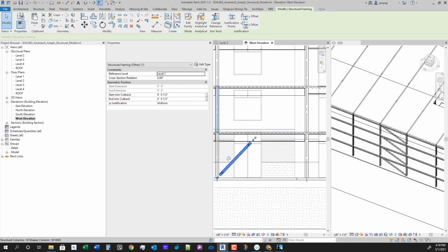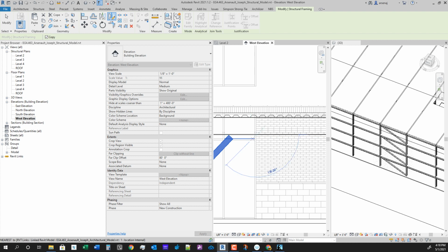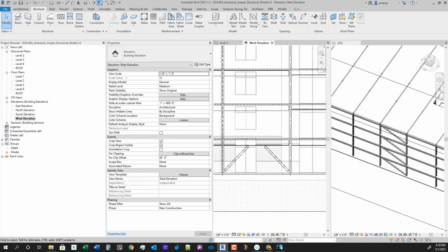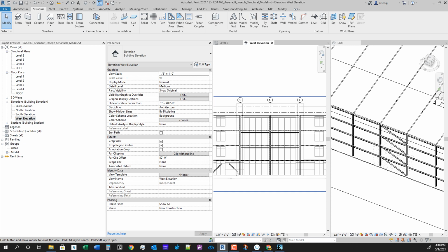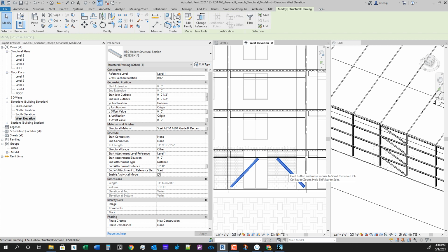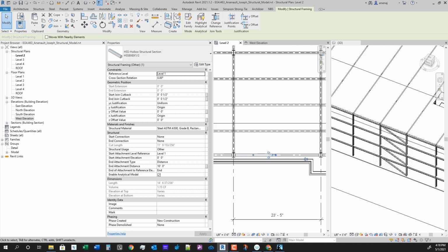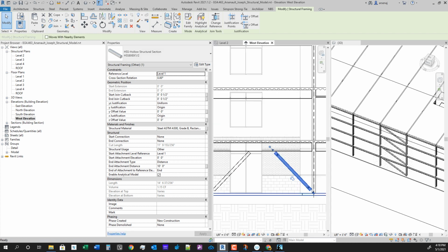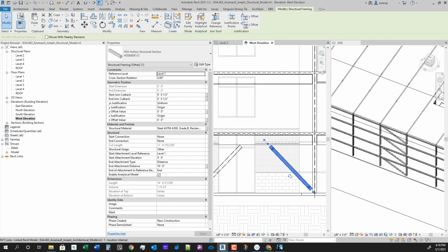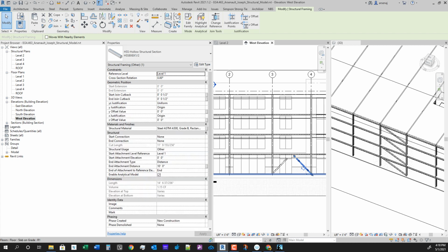It's mirrored in the west elevation view by drawing an axis, mirror draw axis, and typing SM to get snap mid for the center of that beam, and mirroring it to the other side. Again, we'll have to center this up on this elevation.